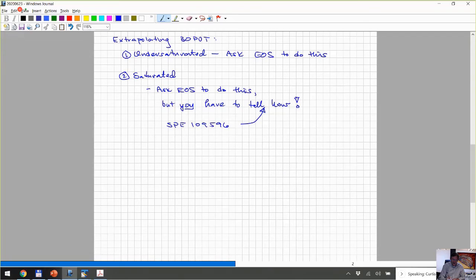But basically you have to use the incipient phase added to the starting composition that you use. That's one way. You can also just recombine separator samples at increasing GORs, for example, to a critical point.